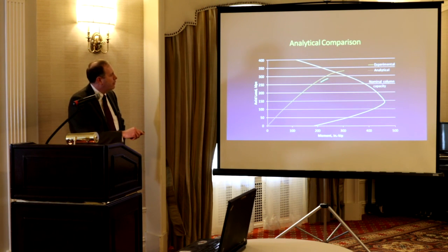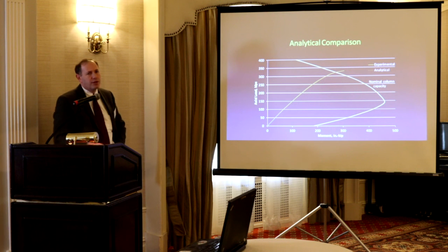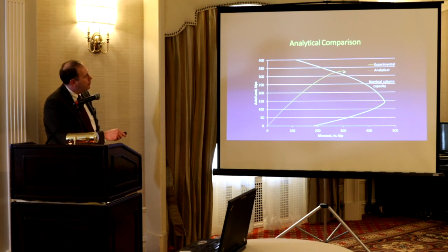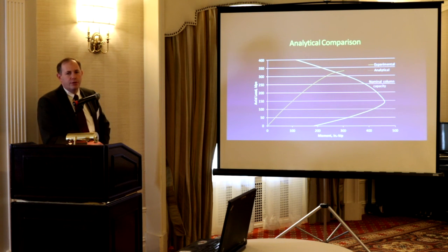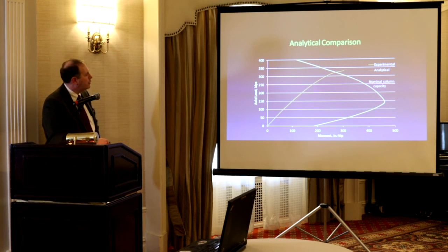And this is the experimental curve. So it comes up load, you see the second order. If there were no second order effects, it would just be a straight line up, but second order effects would come over. And nice, the capacity was predicted conservatively by the code. So that's good. This is where it fails, outside of that curve.